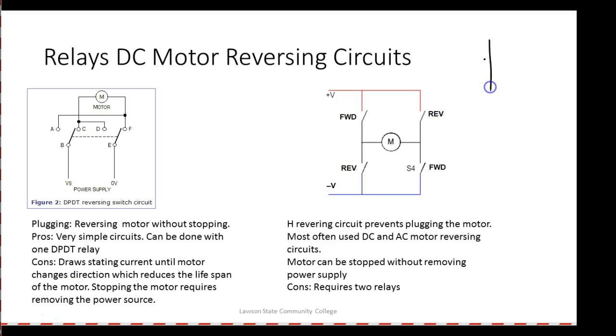We would use one of our outputs, which Stevens calls outputs, I say output 0. Then this output would come over here, and we would have our relay out here. Then this might be output 1. If this one is extend, then the other one would probably be retract, I think. This would actually be a physical contact, this would be R and this would be E, or whatever you want to call it. This is the way we would wire it up.